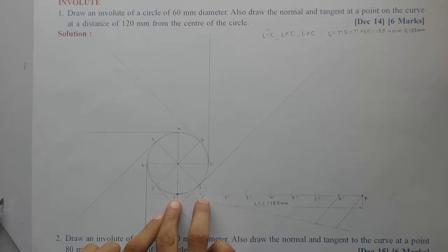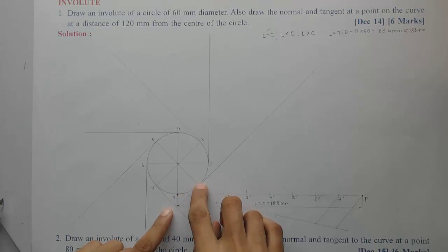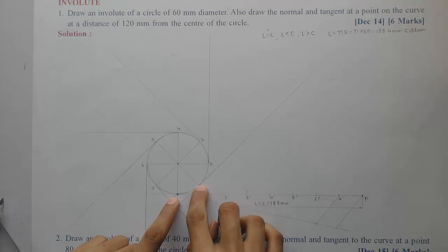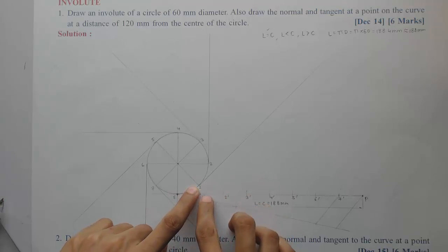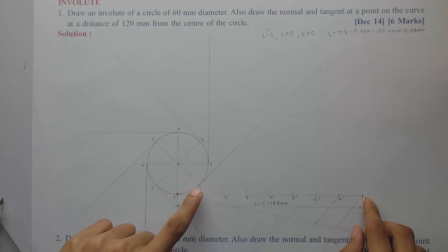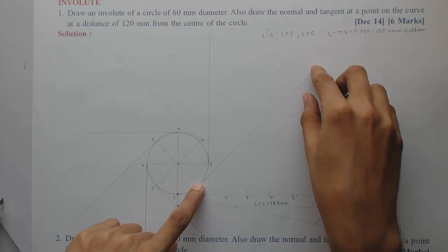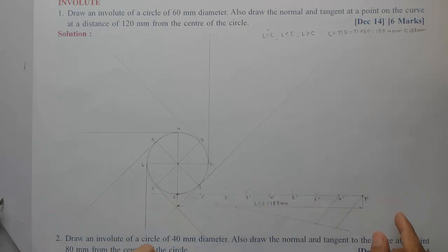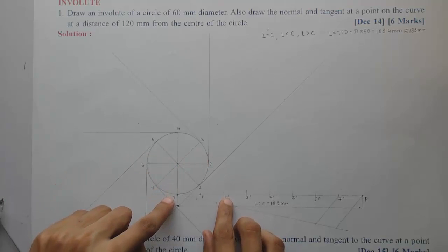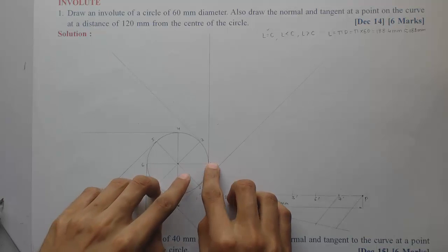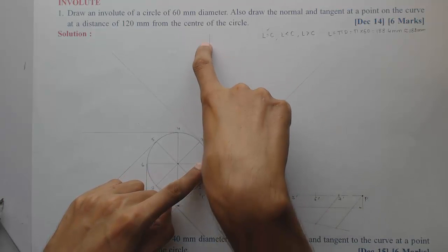But when 1/8, that is this much length, is getting bounded on this 1/8 part of the circumference, this much length will get locked and will not be available for further rotation. So the only available length for further rotation starting with point 1 will be 1' to P. So from 1 I need to mark the 1' to P distance on this tangent. This will be the available length for further rotation. Similarly, after 2/8 rotation, this 2' will coincide with 2, so this much length is locked and not available for further rotation. From 2 onwards, the only available length will be 2' to P. So I need to just take this distance and mark it for further rotation.